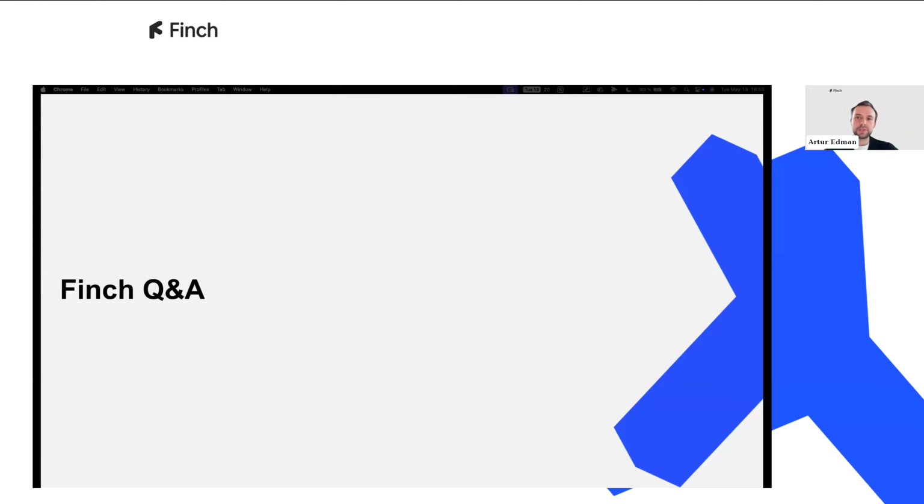And when we work with the unit mix, is it possible to add constraints in terms of minimum facade lengths? Yeah, absolutely. We have a constraints tab that has harder requirements and values that you can input. One of those is minimum facade width for units. One of those is entrance width needed. We also have minimum dual aspect, these sorts of things. So we do have these harder local regulations that you could input for Finch. That's right. And you can find them on the bottom left of the panel with the different parameters that you're inputting.